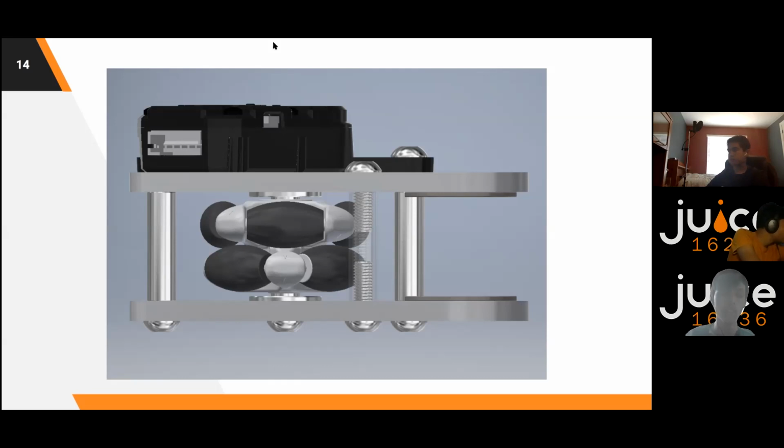But with PID and an odometry system, we would just input that we need to move forward 80 inches or straight 40 inches, put that in as our targets and run it. Then based on the results, we just have to tune the PID values, and that would be the end of it, really. I'd recommend having a testing autonomous where you can just input random values to make sure it does everything right.